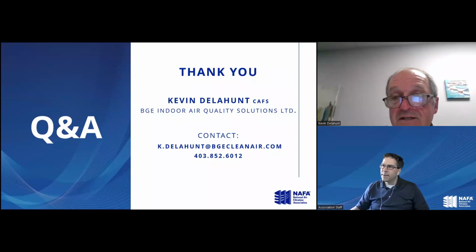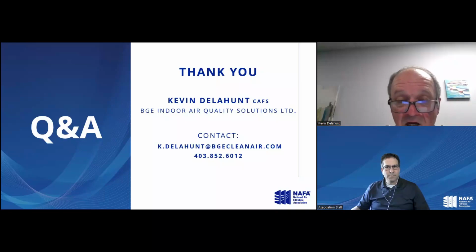In most residential applications, it's probably overkill. If you can get a MERV 11, MERV 13, 14, 15, or 16, it's doing pretty darn good. You're doing a heck of a job in there. So as much as I like to say HEPA filters for everybody, it's not really realistic in today's market.